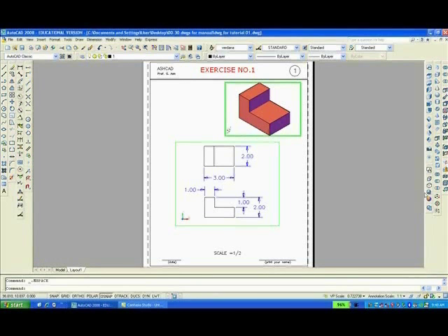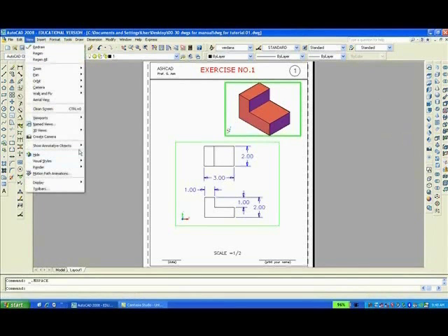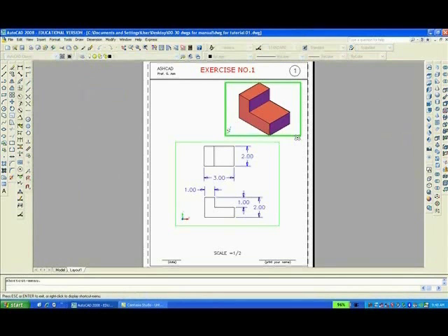Each viewport shows a look inside paper space, and you can do things with them. For example, I can go to View, Orbit, Continuous Orbit, and move this drawing in 3D space any way I want to. In addition, by double-clicking outside of that model space viewport, I can get back into paper space, and I can change the scale to any scale I want for the 2D drawing. You'll learn more about all of that later on as we progress, but right now let's get started creating the